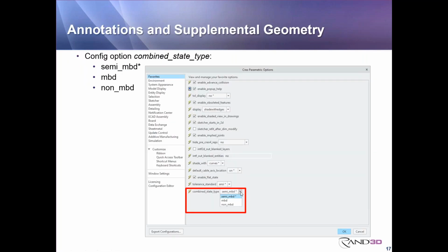From here, as of Creo Parametric 4.0, the M060 date code, your Legacy Datum Annotation Conversion tool became available to help in that conversion of a legacy datum to a datum feature symbol annotation. You can follow the steps outlined here, starting here, to go through that process.